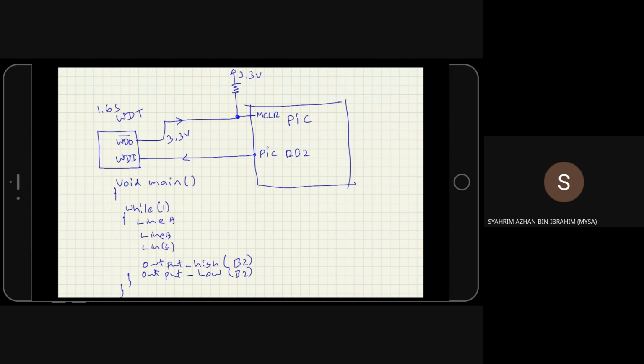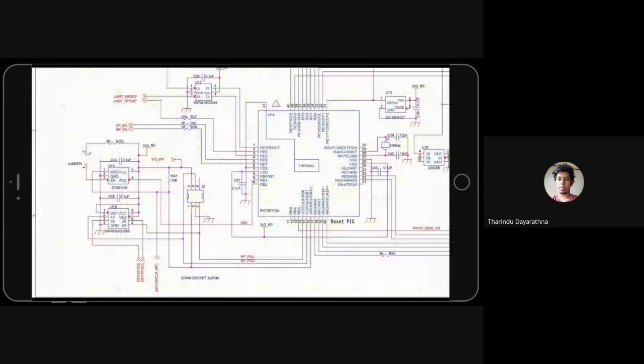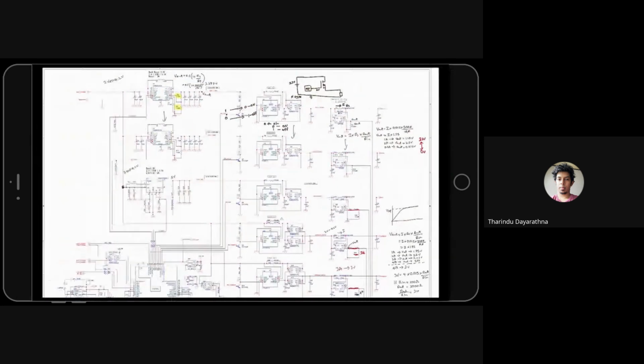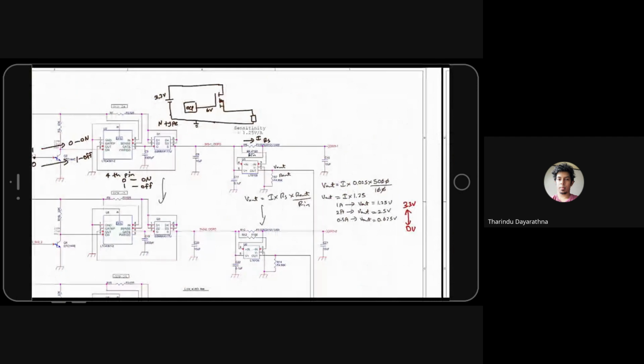I mean the current limit, the OCP? OCP, yes. When you test, I forgot to tell you about some tests. When you get this circuit, please connect a variable load here. Have you seen the electrical load? Yes. So connect the electrical load. You can change the current.